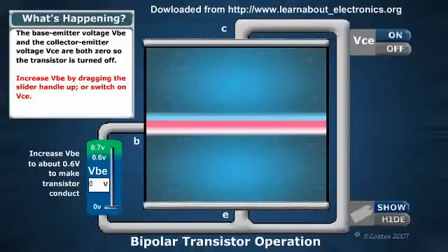With the NPN transistor, we've got a diagram here which shows the collector, the emitter, and the base. The collector effectively collects electrons. The emitter emits electrons. So electrons go from the emitter to the collector. Don't forget that conventional current flows from the collector to the emitter.